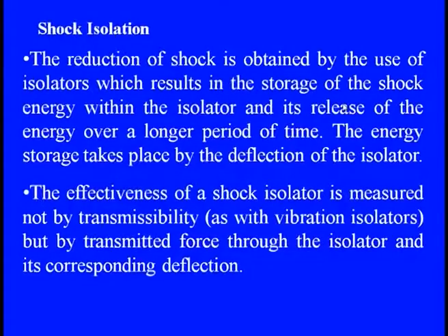If you are talking about the effectiveness of such an isolator, the shock isolator cannot be straightaway measured by transmissibility, where the clear transmission is there. But the effectiveness can be defined by the transmitted force passing through the isolator and its corresponding deflection.